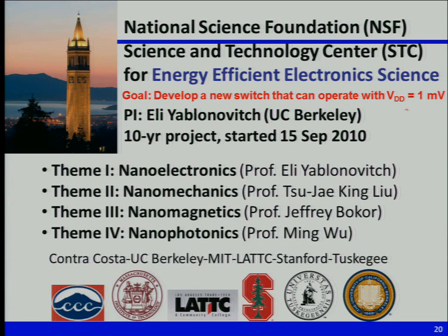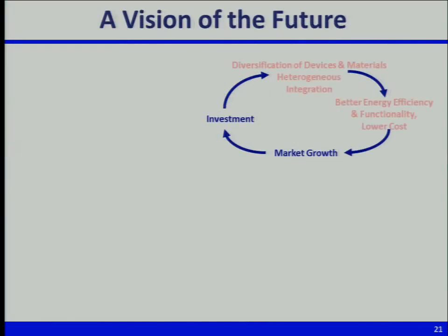So today we're working on transistor designs that can operate well below 1 volt. For the FinFET, people project you can go down to half a volt. So you can reduce the power supply voltage by a factor of 2, and lower active power consumption by a factor of 4. Today we're looking at research trying to go down to millivolts operation to save a lot more power. If you're interested in that, I can tell you about that.